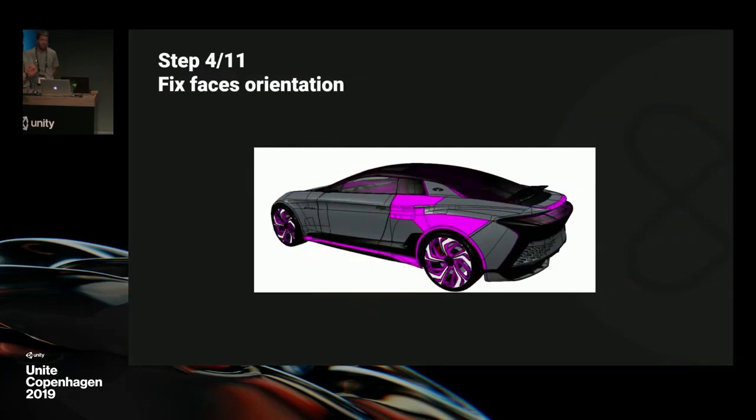And face orientation is really a big issue in data preparation. So it happens very often that some faces are not oriented correctly, even after repair mesh, as Cédric said. So see the pink faces here. These are misoriented faces, meaning transparent from this point of view. So if back face culling is on in Unity, we will see through the car body, which is not what we want, of course. And reorienting faces correctly is also a performance matter, since it will let the real-time engine, so Unity, do back face culling, so it's important.